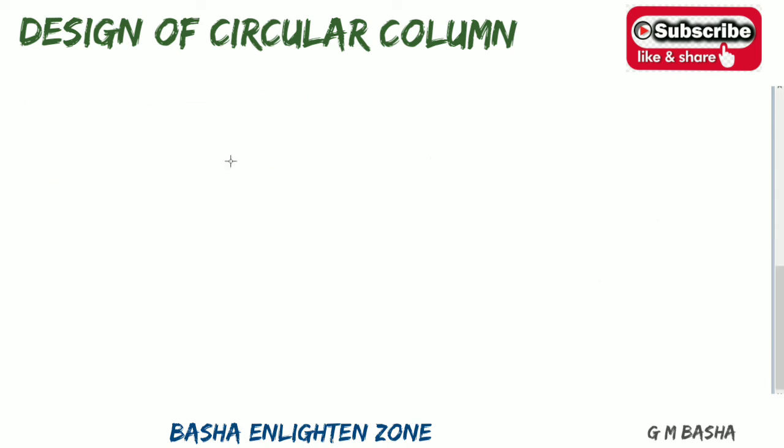So here we are using 6 bars, so circular column of 430 dia, and actually first they are providing longitudinal bars, then stirrups, but here I am taking that stirrups will be first. Okay, with some giving of cover gap, and again I am providing the 6 bars with equal spacing.